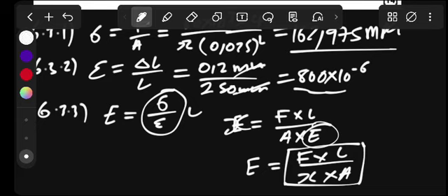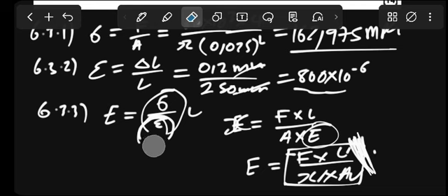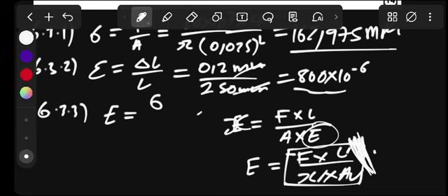Okay, also, this is good. Remember the force, we did not calculate the force. We're given the force, we're given the length, we're given the extension, we've given the area. Yeah, this is safe because everything was there. It's a safe one. If it might happen that your strain is wrong, you are in a mess. So Young modulus, you can start by using that.